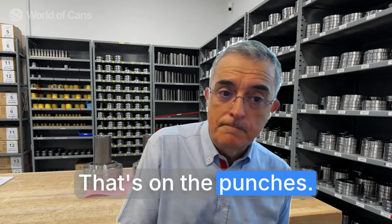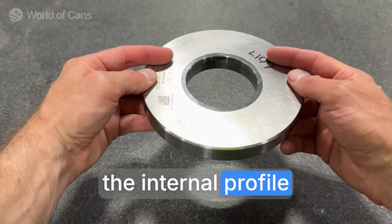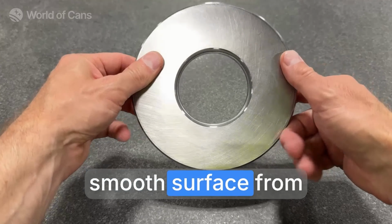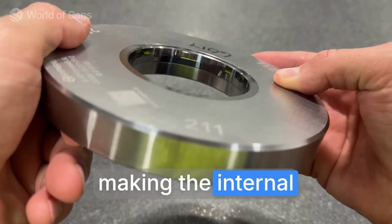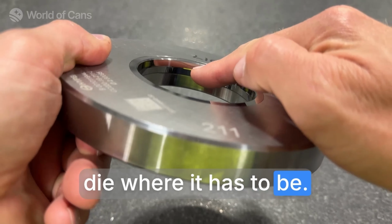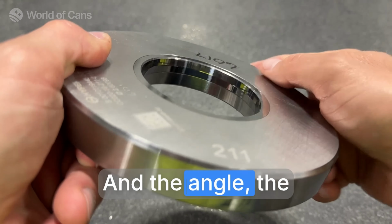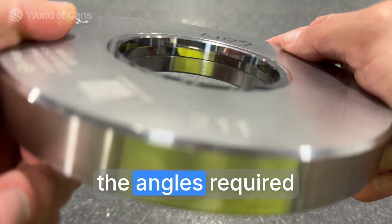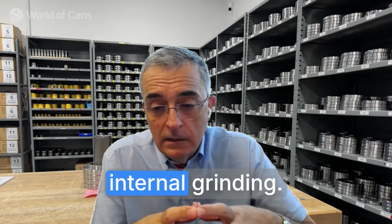That's on the punches. On the rings, it's about grinding the internal profile of an ironing die, giving this extremely smooth surface from the grinder, and making the internal profile of an ironing die where it has to be. The position of the land has to be in a certain location, and the angle, the inlet and the outside angle, must meet the angles required by the customer. And that's what is achieved by the internal grinding.